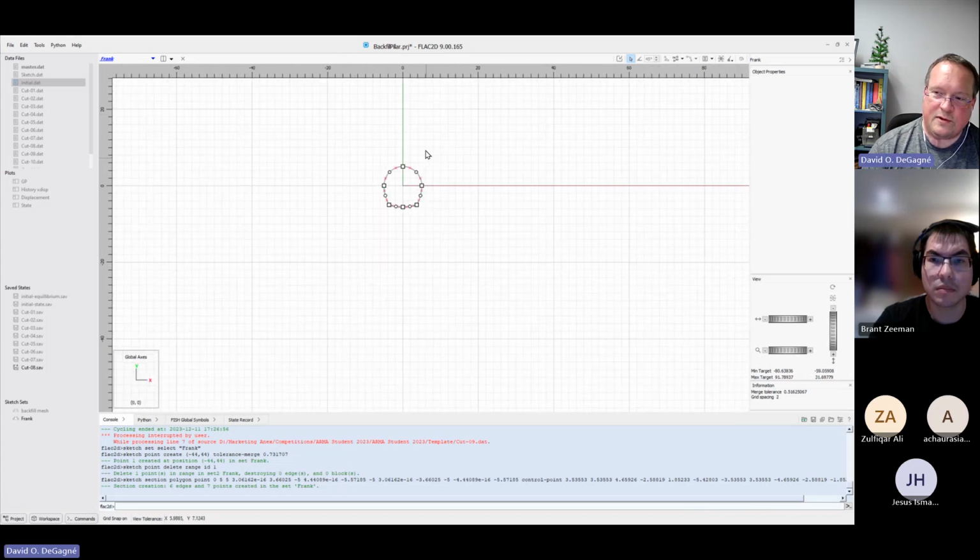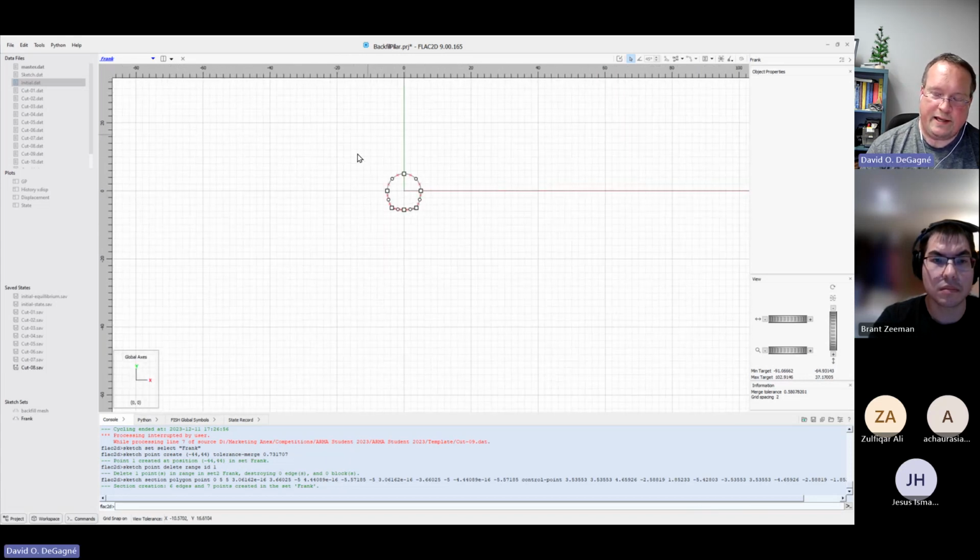And then sometimes there are little tricks that we need to play by creating different boxes. So if you wanted to have very fine zones around the tunnel, you might put a box around that, specify you want 1 meter zones or half a meter zone length, and then have another box around that that's specified to be twice as big.